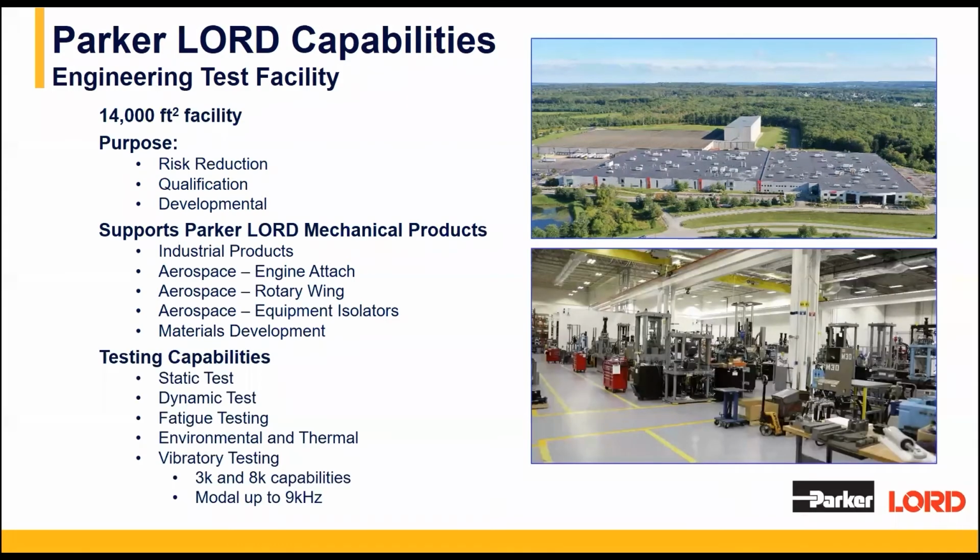Some of the testing capabilities include static testing, dynamic testing, fatigue testing, environmental and thermal testing for DO-160 or MIL-810 type requirements, as well as our favorite vibratory testing with shakers. We have both 3K and 8K shakers and some modal shakers up to 9 kilohertz.